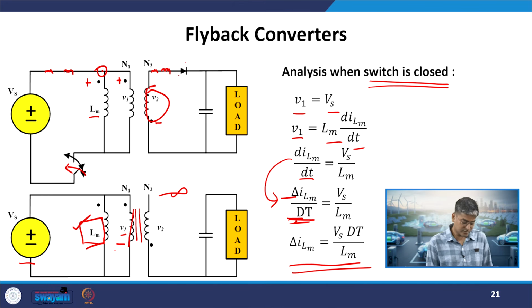Now, in this case, what is this magnetizing inductor? It is the one which denotes the flux lines of our transformer core. So, if Lm is having some finite energy, that is half L ILm squared over here, what is the meaning of that? If it is having some finite current through it, it means the core is having some flux lines inside it.